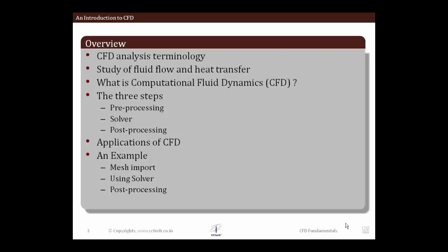Well, there's a lot of discussion about this, but I would say CFD is better described not by the conventional name computational fluid dynamics, but rather flow dynamics, because you can capture fluid flow as well as heat transfer, or so to say, flow of any phenomena can be captured computationally, and that's what we are analyzing in CFD. It is a three-step procedure, which includes geometry creation and meshing as part of pre-processing, solving the equations which govern these phenomena, which are usually encountered in flow dynamics, and doing an analysis of it based on post-processing.